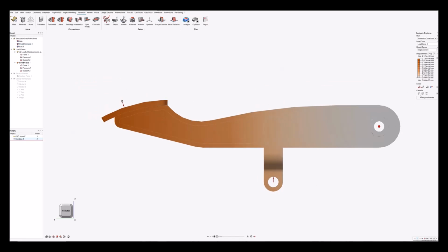I've already done this, but I can use the callout tool to create callouts to place data at specific points. This is reading the field that is the results of the simulation. At these discrete points, we capture the stress or displacement, and then we can use this in field-driven design later. There's an option to view the data from each of the callouts in a table at the bottom of the